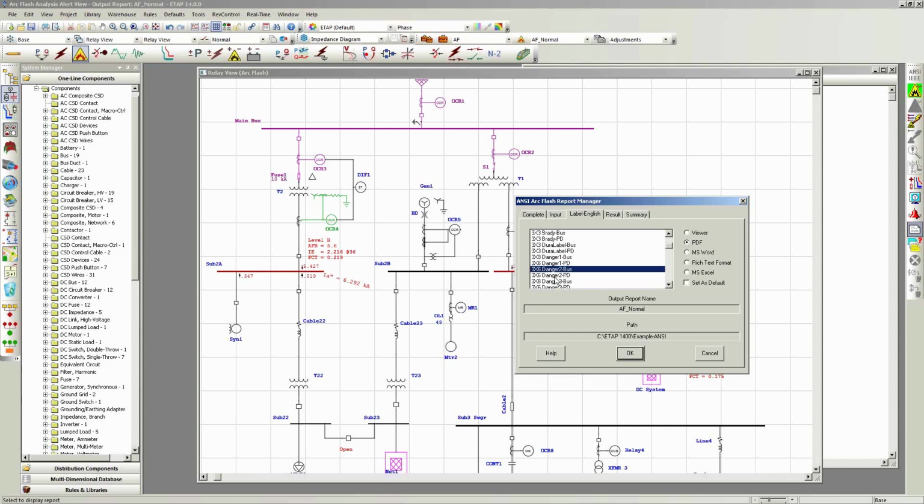Okay, so moving forward with the naming convention, after you look at the warning or danger or the manufacturer, you'll also see a number that is the template. So for example, for 3x6, you have danger 1, 2, 3, 4. Those are 4 different templates, just a different layout, a different way to express the Arc Flash label. And then you have a bus and a PD. So again, bus is if you're going to be labeling the line side, if you're going to be exposed to the line side, or PD would be for the load side, or load breakers.